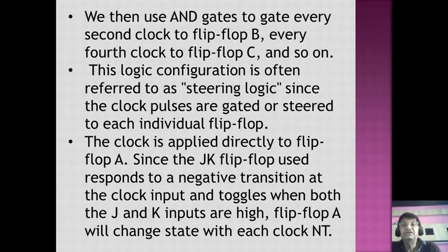We then use the AND gate to get every second clock to flip-flop B and every 4th clock to flip-flop C, and so on. This logic configuration is often referred to as steering logic, since the clock pulses are gated or steered to the individual flip-flops.